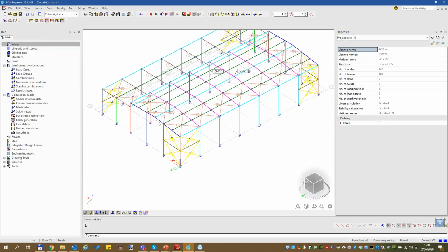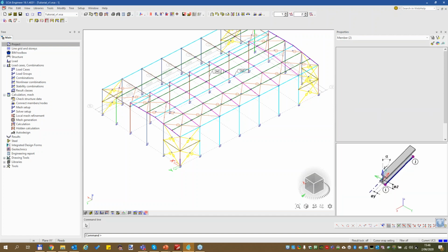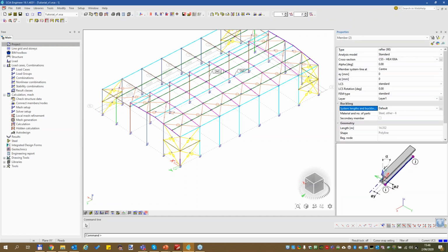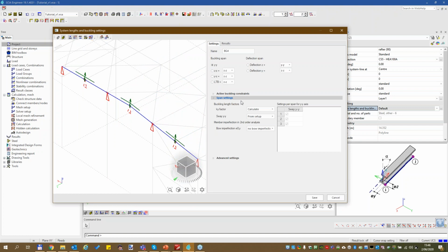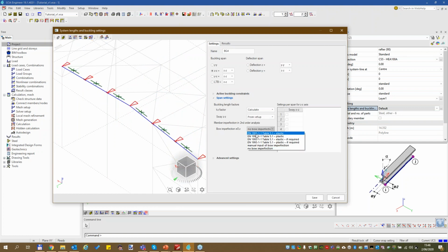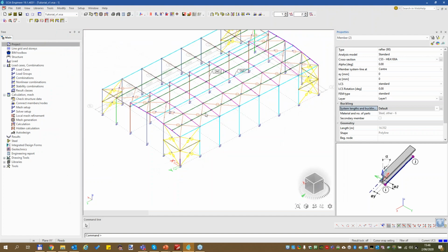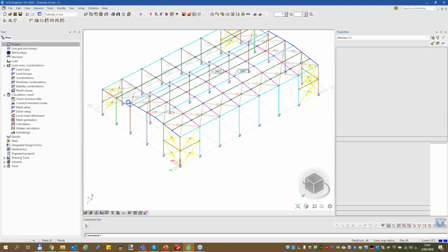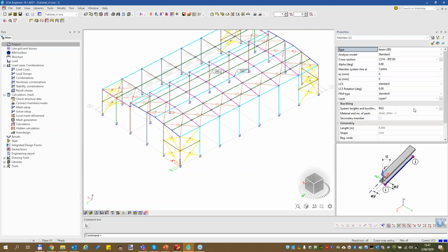And I can give these two dedicated ones by switching them to default and then clicking on the three dots next to it. It will automatically create a new one from scratch. And that one will be normally okay, buckling restraint wise. Again, here the same. Like this. Need to do the same here. So let me just quickly do that one directly.